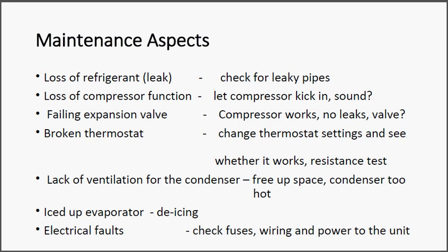You could have an iced up evaporator on the inside. Again, the energy cost goes quite high because it still tries to evaporate, to cool down, but if the cold air can't go anywhere because it's all iced up, you will find that a lot more energy is used up with your fridge.